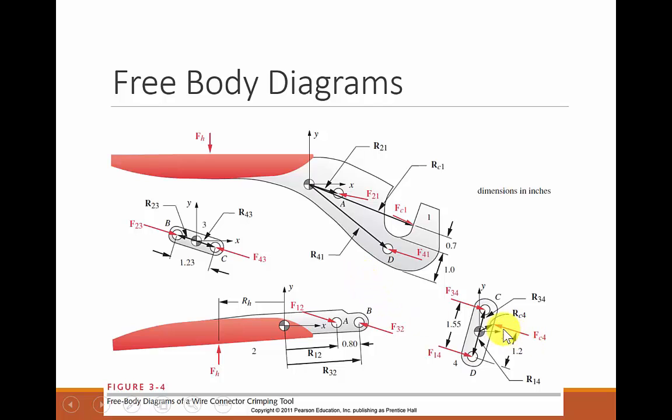Given this force right here, and assuming statics, so assuming that we're not moving at this point, we could calculate all of these forces. Once we have these forces, now we have enough information to calculate this force. Using this force and a relationship right here, now we can calculate this force. And using all of that information together, we now can calculate this force and finally back out what FH actually is. Okay, so there's a quick reminder about what free body diagrams are.